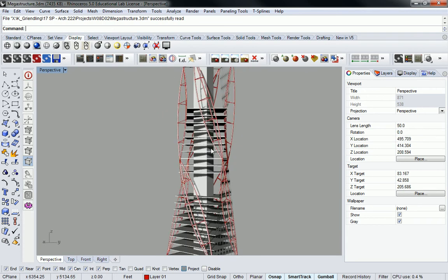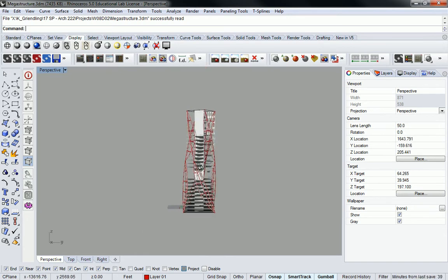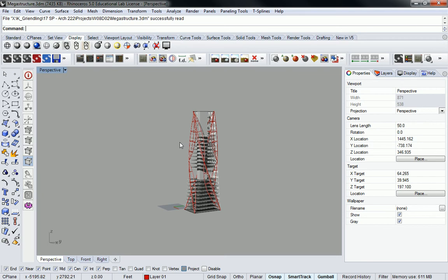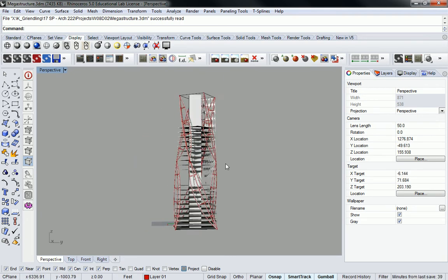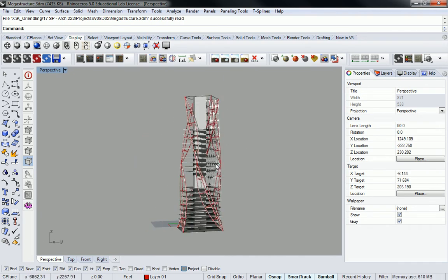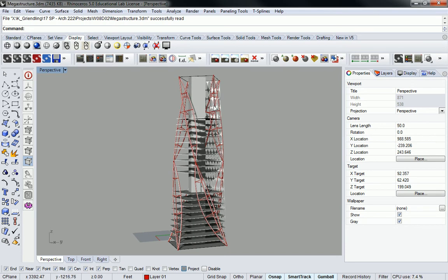So first and foremost, I think one of the things that throws me off about this building is that structurally it's a little weird, right? We have these tilting, twisting structural columns, and there's nothing holding them up except the diaphragm of the floors, which would just twist and crunch if you were to ever put any compression on it. So yeah, when you're doing these kind of quadrahelical things, that's what's going to happen. But anyway, what we need to do for that is actually incredibly simple.